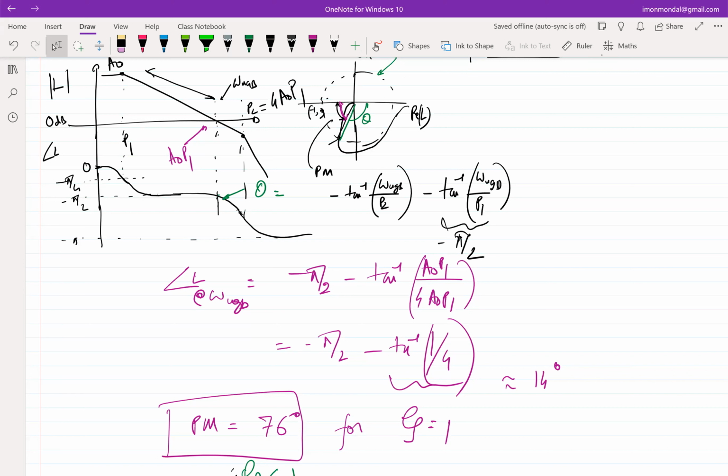Fine. So in order to do that, in this particular circuit, we had to split the poles. How did we split the poles? We saw that we couldn't reduce capacitance. So we had to increase capacitance in order to move one pole to a lower frequency. And moving a pole to a lower frequency essentially means what? I am adding more capacitance, which means I am slowing the system down.